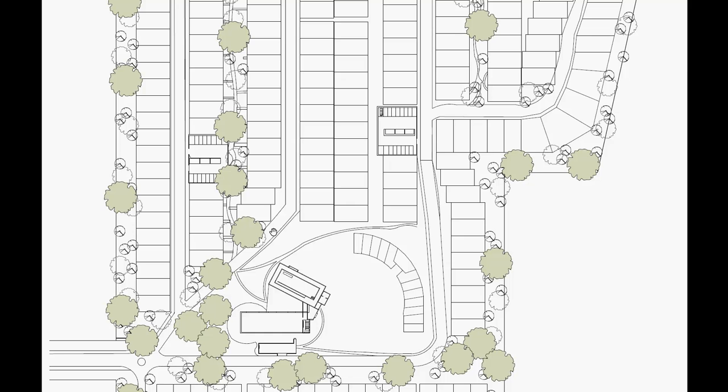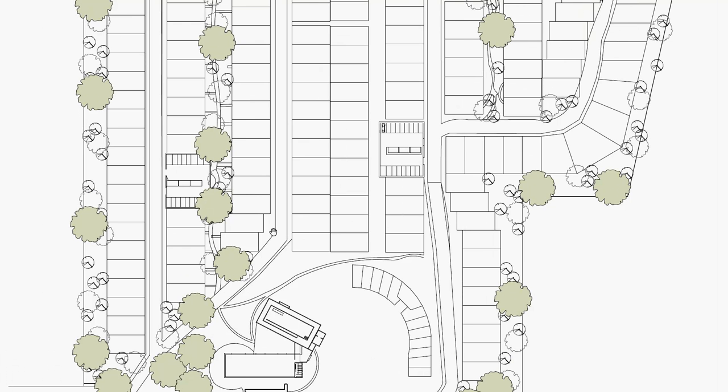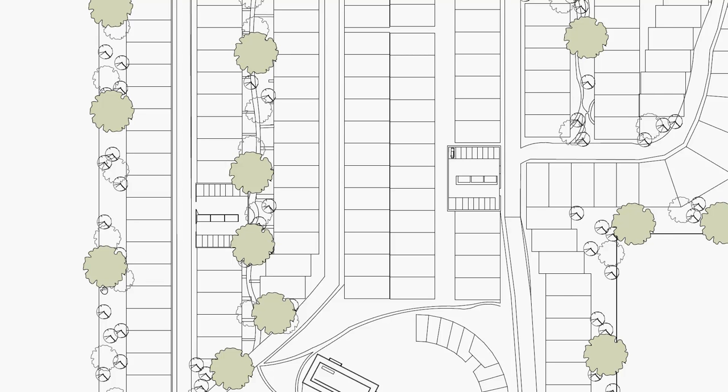Here is the result printed high resolution to CutePDF. I'll just zoom in a little more, and this is the zone that we've been talking about. So that symbol we just edited, picked a fairly soft green, although I think we could have gone for a paler green. But notice what happened to the other two symbols, they did not print. So as soon as you use transparency, you can't use the conventional PDF writers. We would love to find one that did print transparency, and we do keep on looking.